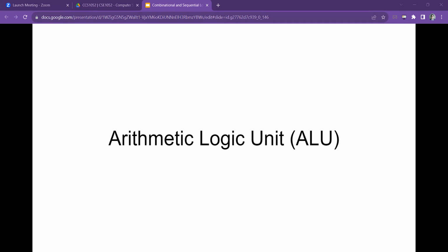But this is actually what will happen in the ALU. But let's say we need only one particular output, such as the summation. That means we need a switch. So these outputs will come to this multiplexer, and there will be only one output.